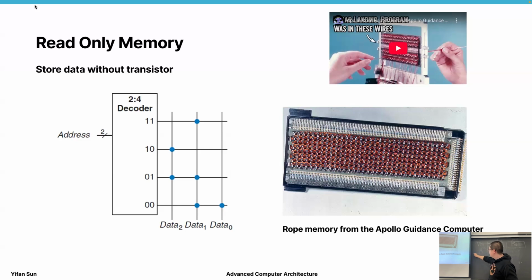This is the bit line. So the bit line goes through this magnet, or it goes past this magnet. If it's going through this magnet, whenever this magnet is enabled, we will detect the current on this wire, right? So in that case, this is a 1. If it's woven outside this metal circle, it cannot detect the change, so it's 0. So that's how this ROM works.